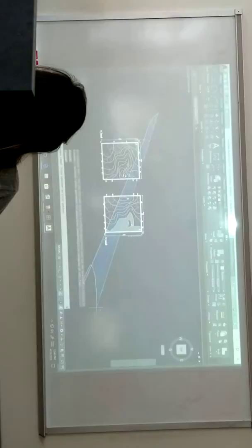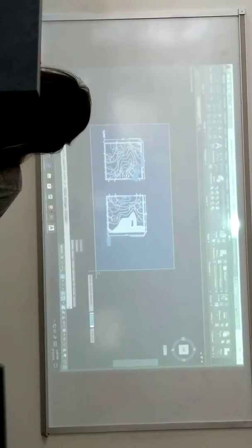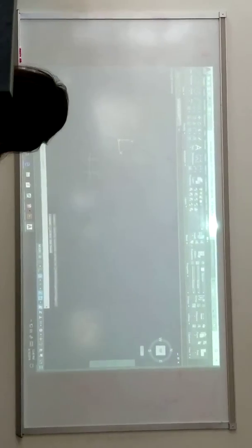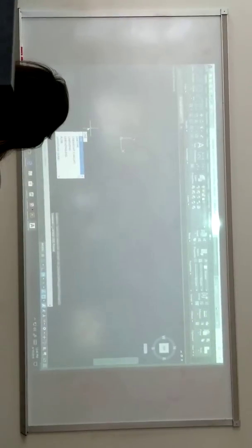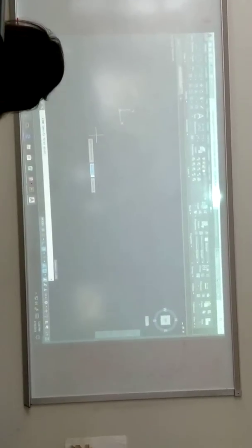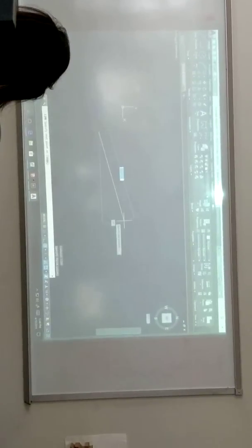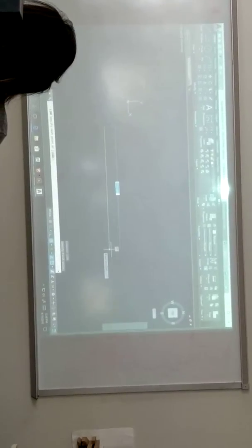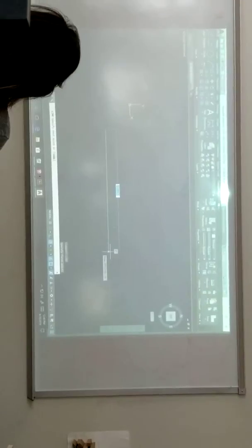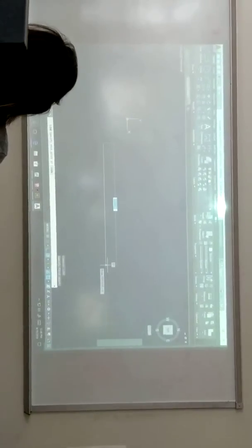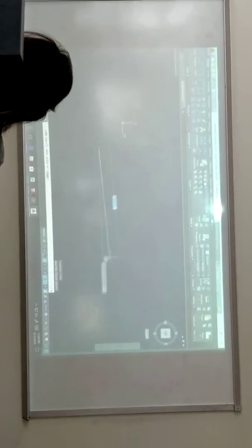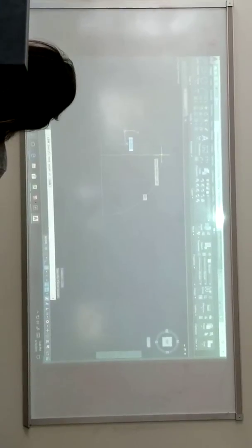I would delete this. So AutoCAD is better at drafting. I can draft so much easier in AutoCAD. I can type in line, and it has what's called polar tracking. It tracks what I do, similar to what SketchUp does. It lets me know as I'm moving, this is how far you are. And this little green dash is telling me that you are on an orthogonal plane or an orthogonal axis, okay? Polar tracking helps with that. Now I know I'm at 90 degrees going this way.